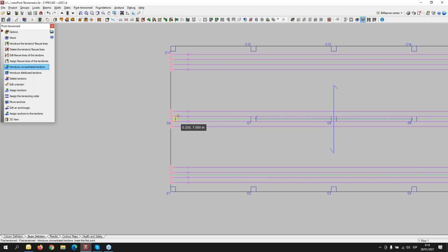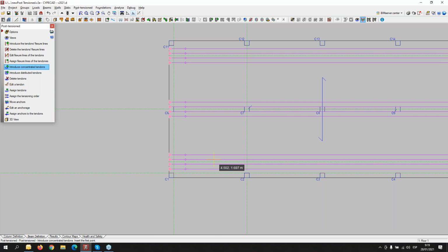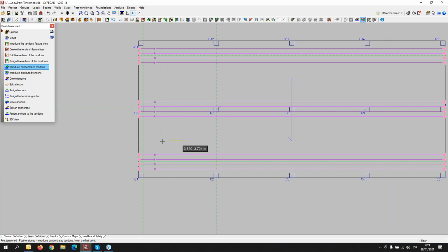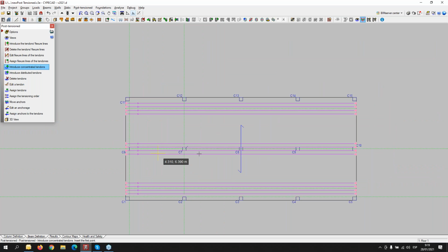So when a flexure line appears and a tendon crosses this flexure line, the natural position of the tendon will be at the bottom of the slab. Okay, so that will be very, very important in order to obtain the position of the tendons and the application of the forces of the post-tensioned cable.